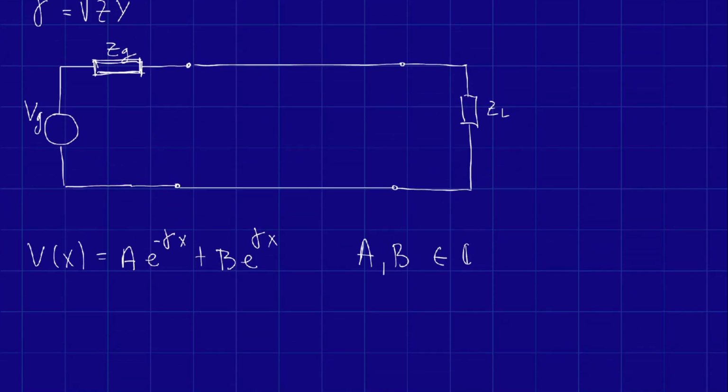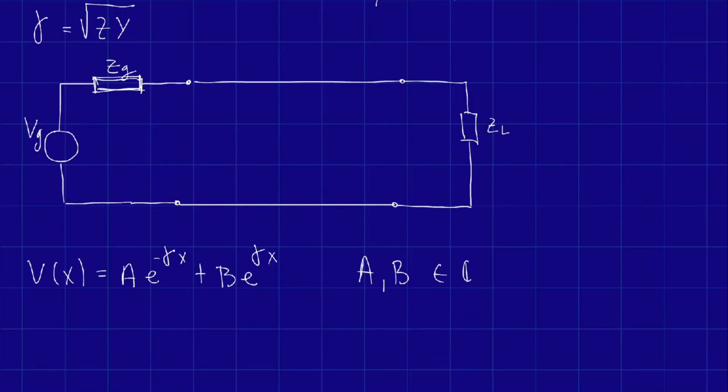And an interesting thing about transmission lines that we are not used to before is that the wave will arrive at the load, but it is not certain that all of the wave will be absorbed. Some of the wave might get reflected. In some cases, which are bad cases, all of the wave will get reflected. So this part right here is what we call the direct wave, and this right here is what we call the reflected wave, which is something that is unwanted in most cases.